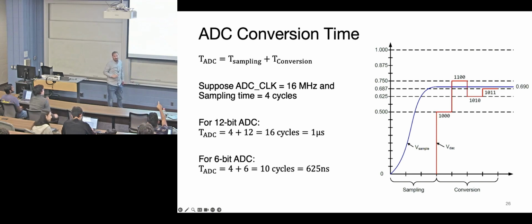You have the clock speed up there. And you know what the duration is. Oh, clock speed, yes. And you multiply that by 10. Yeah. For a second, I misread that, misunderstood what that was. Does that make sense? So really, it's figure out how many clock cycles it takes, right? When you figure out the clock cycles, and you know what your clock speed is, then you can figure out what your conversion time is.